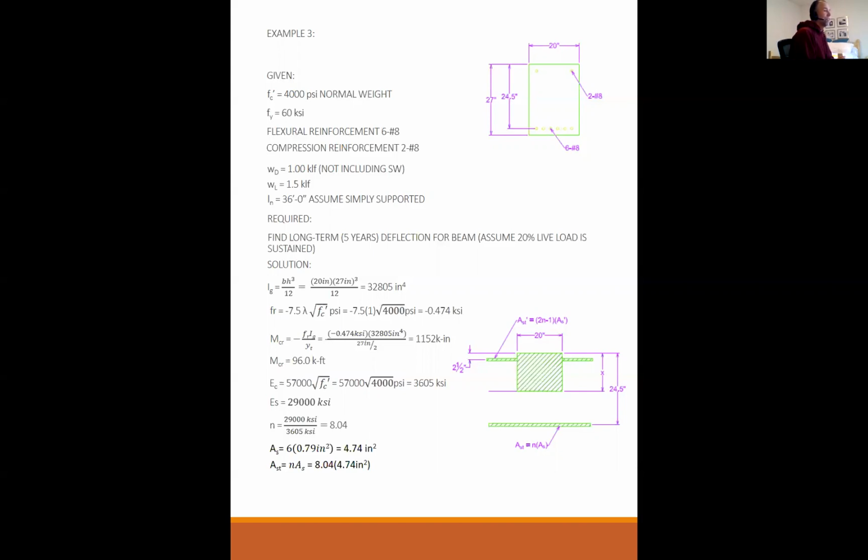Actually, the neutral axis is at little c, not little a. That's the ultimate state. If little a is below the bottom of the flange, then it's true T-beam behavior. If little a is into the flange, then it's rectangular beam behavior. But all of homework number 4 in its entirety is limit state.